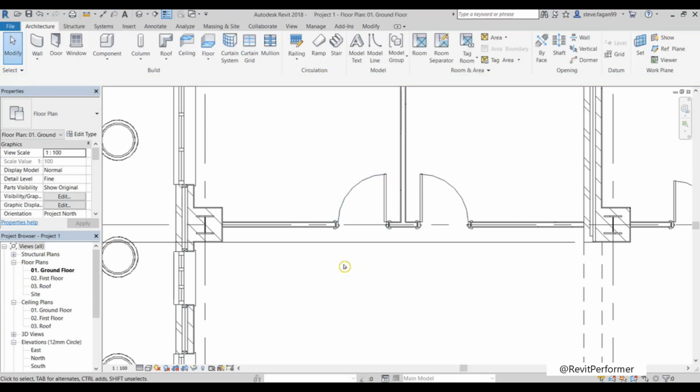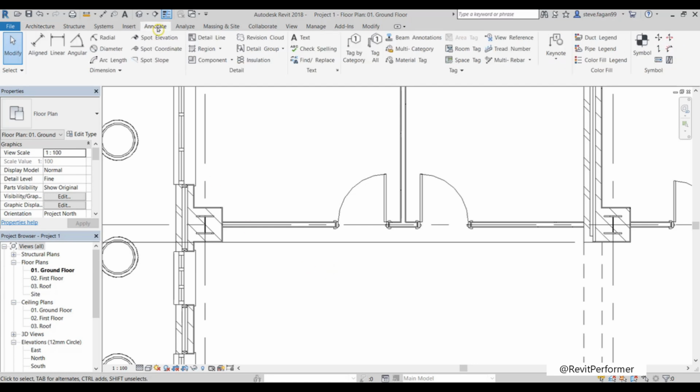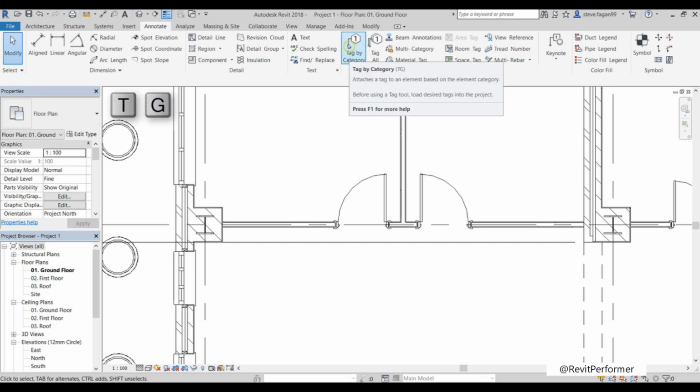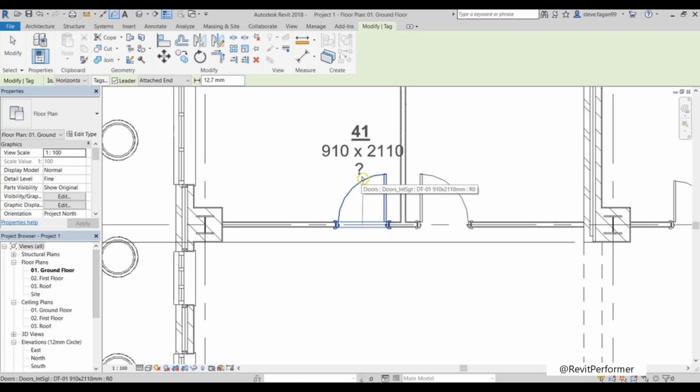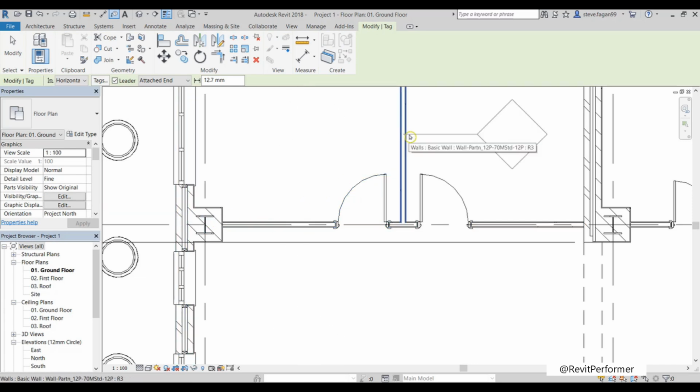and then press escape. So now our tag is in the drawing itself, and now we can start the tagging process. We'll go to the annotate tab. There we have a tag panel. What we're going to be looking at today are the tag by category and tag all. So if we use the tag by category, it'll tag individual components as we select them. As long as we've correctly attached the correct label and specified the right information, the correct tag will appear.